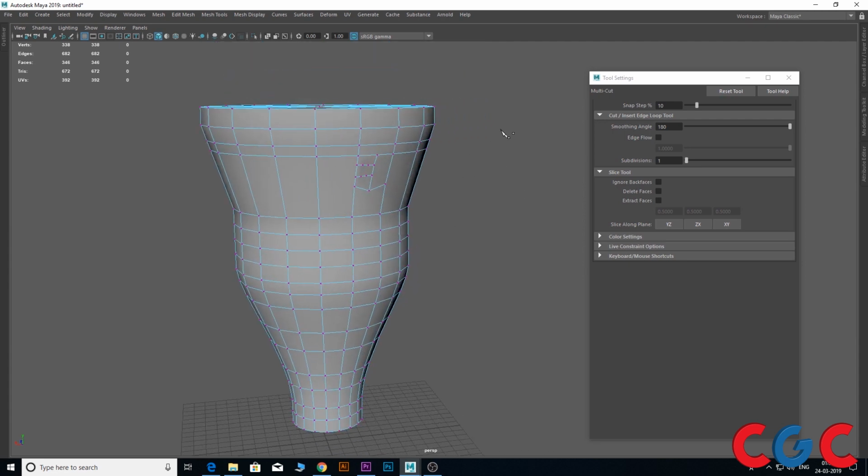I can just press outside, shift, left click. So I can see there is a long slice. This will help me to see where I can create the loop. It is moving in 10-degree angle. When I increase this value to around 25, you can see I'm just pressing outside, shift. You can see it is moving in 20-degree angles, 25-degree angle. If I go with 45 degrees, shift, I can see this is moving in 45-degree angle. If I am not holding shift, it will move freely.